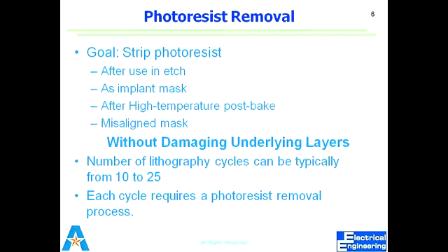In lift off process, before the deposition of the thin metallic layer, you spin on photoresist. You pattern a photoresist and then you deposit the metallic layer that you want to pattern. This is silicon wafer, and let's suppose that this is the photoresist. I put the photoresist, I pattern it. I spun photoresist, do the photolithography, open this area. So this is the photoresist.